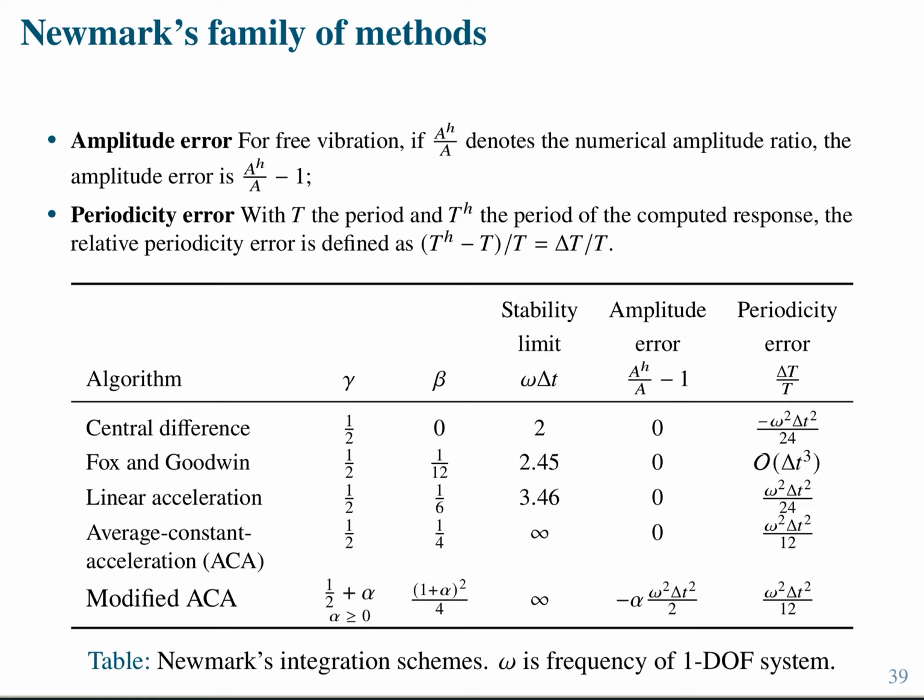I particularly like implicit integration schemes because we do have some convergence, right? So in order for me to get the solution of the system at n+1, I need to iterate. And until I get that equation satisfied, I am not done iterating. But when I converge, I can guarantee that the solution at n+1 is going to be the right solution. Now, is this easy? It's super hard. Why is it hard? Again, because of the reasons you just said, right?